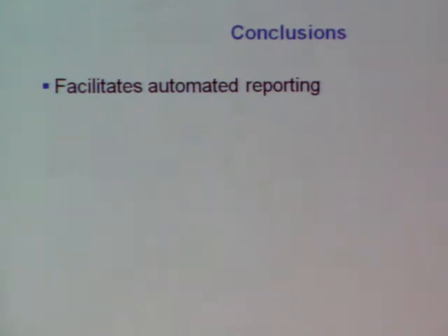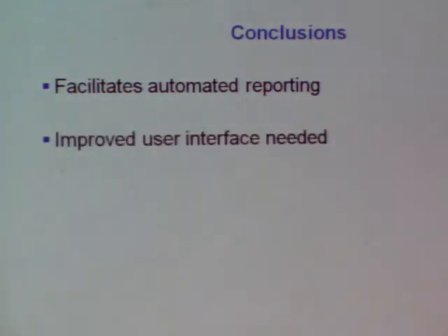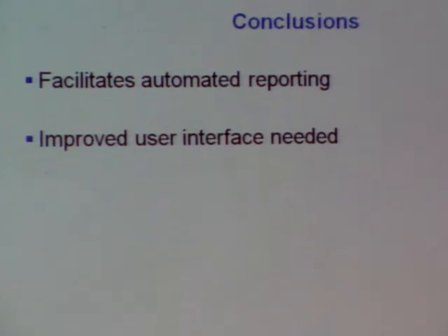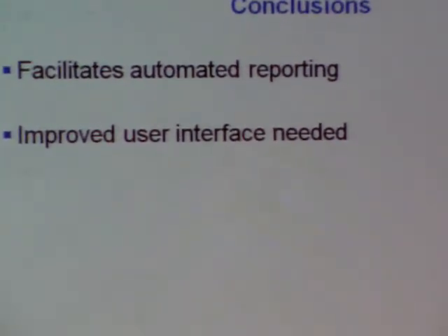The need for improved user interfaces has been clear during this project. The present mandatory equipment does not support presentation of ASMs, and this must be taken care of. For position-related information, ECDIS may be the appropriate presentation system, but for non-position-related information, a bridge computer with dedicated software, as Marcus mentioned, may be the best way. And that could also give an early implementation without waiting for new standards to be developed and implemented.